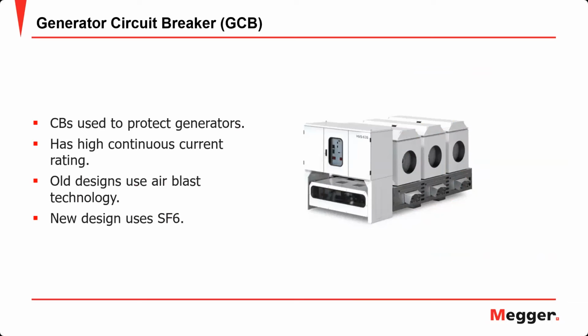The final type we'll discuss today is the generator circuit breaker, or GCB. It is used to protect generators and has a high continuous current rating. Older designs used air blast technology, and the newer designs use SF6 gas.